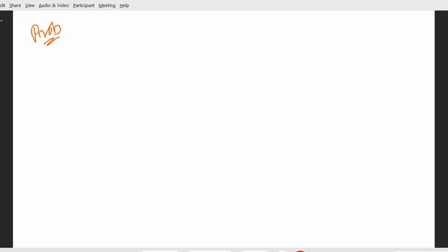Okay, firstly, what we have is our ring, right? And this is the internal one. And here we have a thickness of 10 mm, right? We have to determine the mass moment of inertia about an axis which is perpendicular to the page and passing through the pin. That is, where is that pin? Here is the point O, perpendicular to the page, which is tangent to the circle and which is passing through the point O.